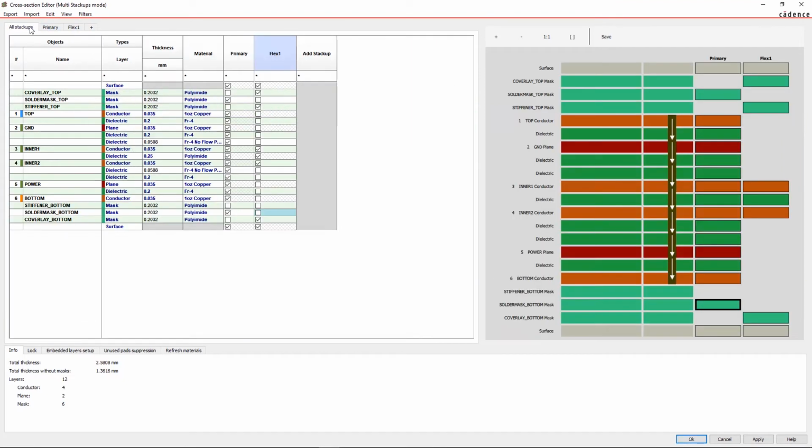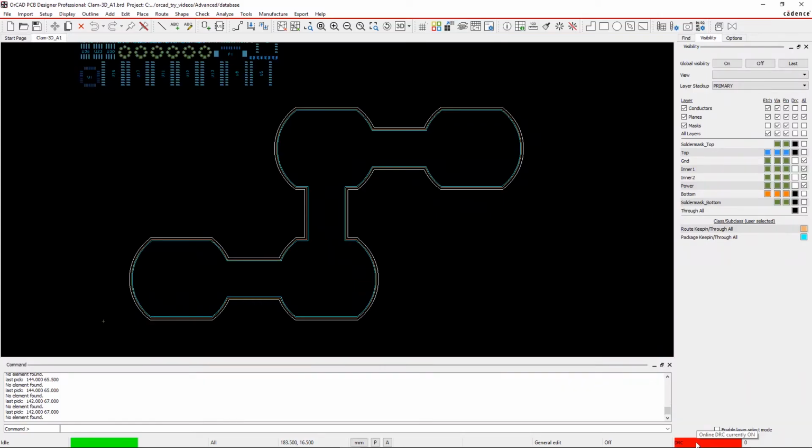Notice that you need to create a base stackup which has all masking and etch layer information for the stackups you plan to create in your design. You can create a library of base stackup XML files and import them when designing a new stackup. You can also refer to stackup information from your manufacturer.